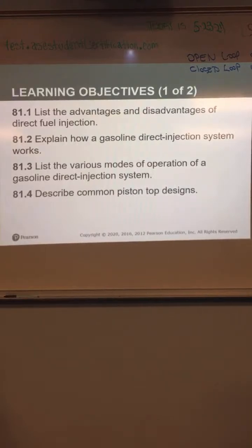So, it sounds like there's quite a few advantages. What about disadvantages? Is there any disadvantages to that system? Higher cost due to high pressure pumping and components. Yep, higher cost, more components. Due to the high compression, a NOx storage catalyst is sometimes required to meet emission standards, especially in Europe, and it uses up to 6 operating modes depending on engine load and speed.